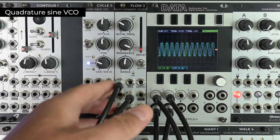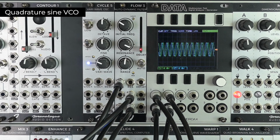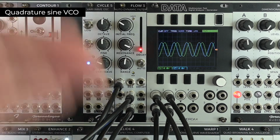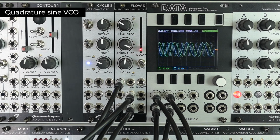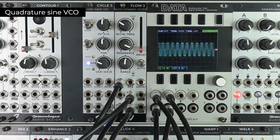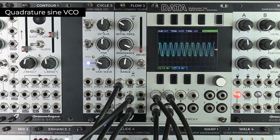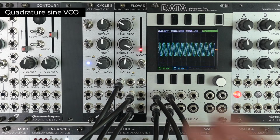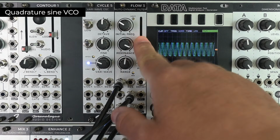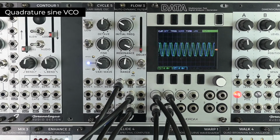You can even send in negative CVs to the frequency modulation input to get Flow 3 into sub-audio rate territory and use it as a quadrature sine wave LFO. Of course, there's also modulation inputs for the resonance as well as the decay setting, which also affects the slew of the built-in envelope follower.